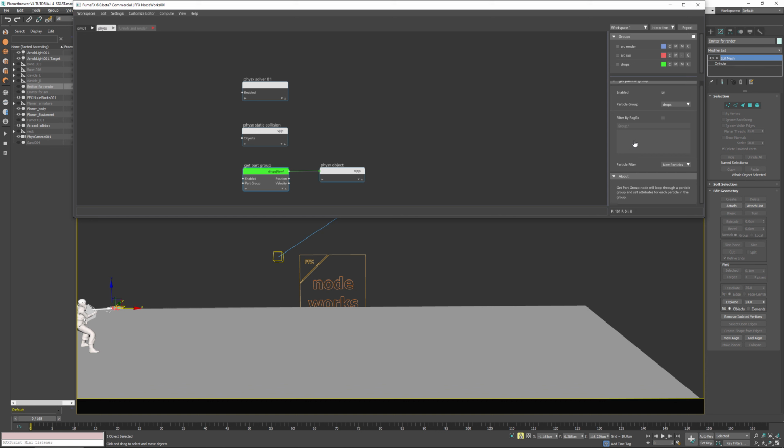So drop particles are connected to the PhysX object, which is now sim group 1, and they are going to collide with sim group 0, which is the static collision. It's going to be a dynamic object, type of sphere, with a radius of 1, also 0 bounce, and static and dynamic friction set to 10.